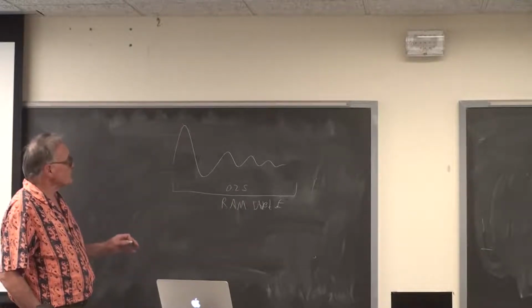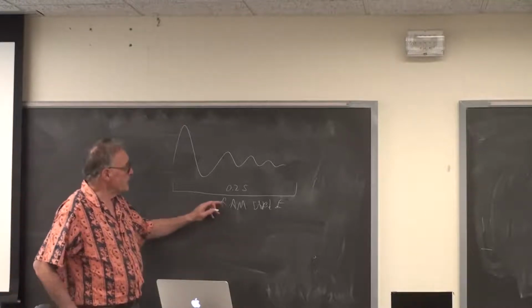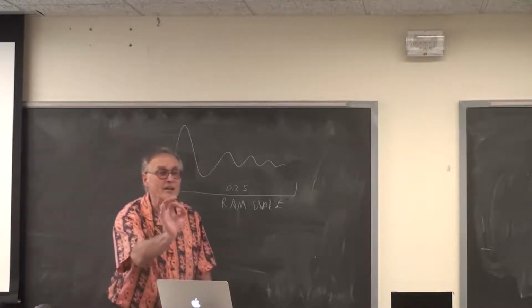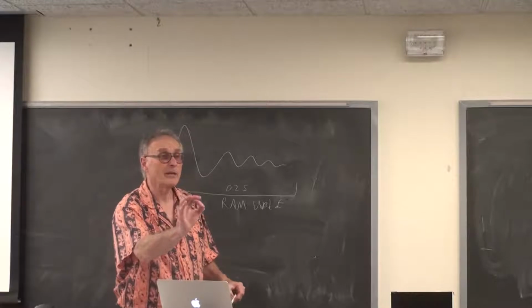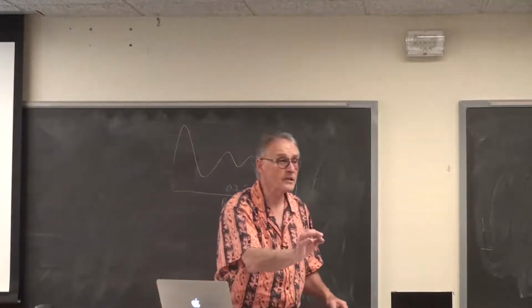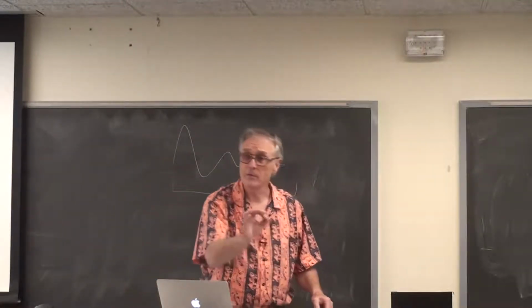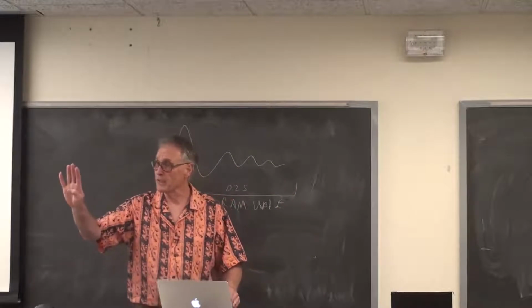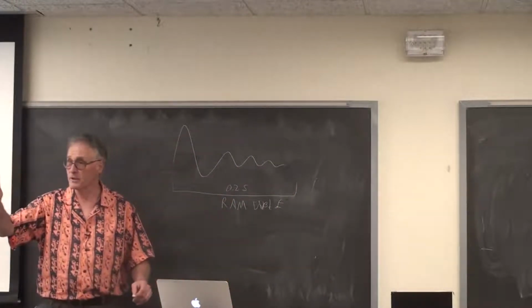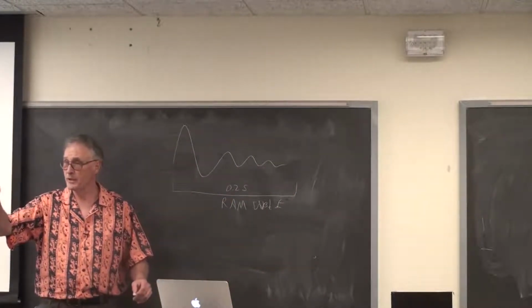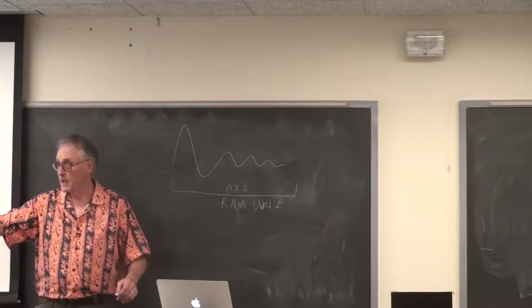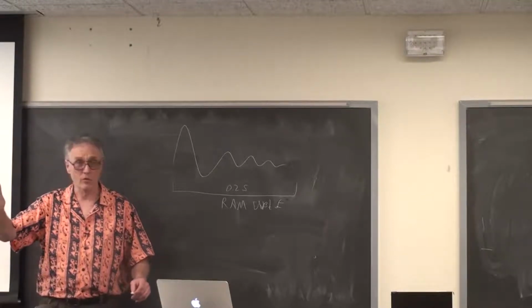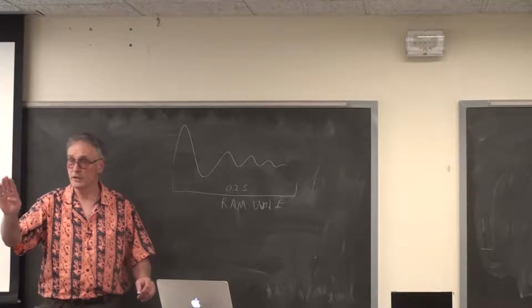And the RAM table is going to have the entire waveform, and it's going to have embedded in the waveform the control bits for the DAC. Remember, the SPI DAC has 4 control bits at the top. The high 4 bits are control bits. There's a 12-bit DAC, requires a 16-bit word, and the top 4 bits are control bits.